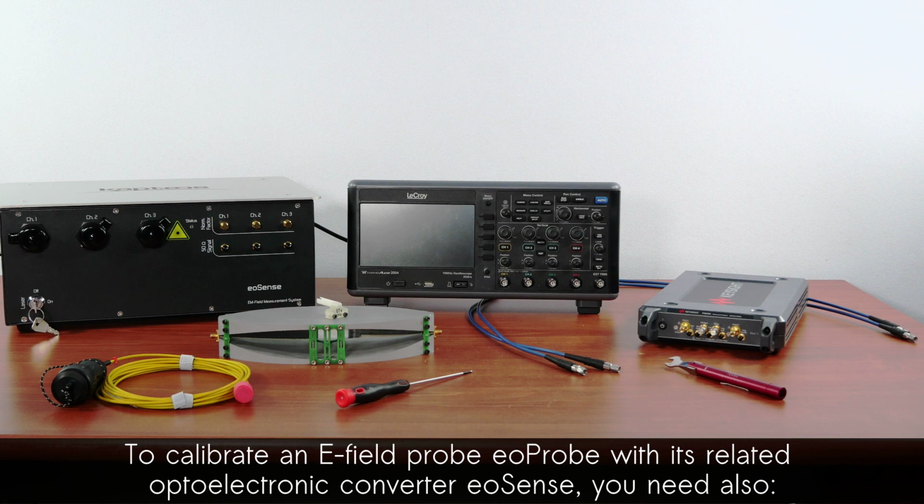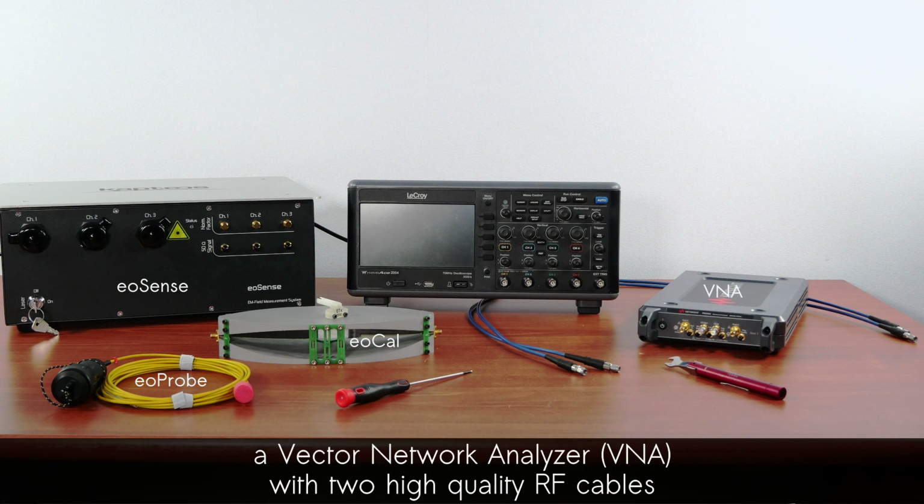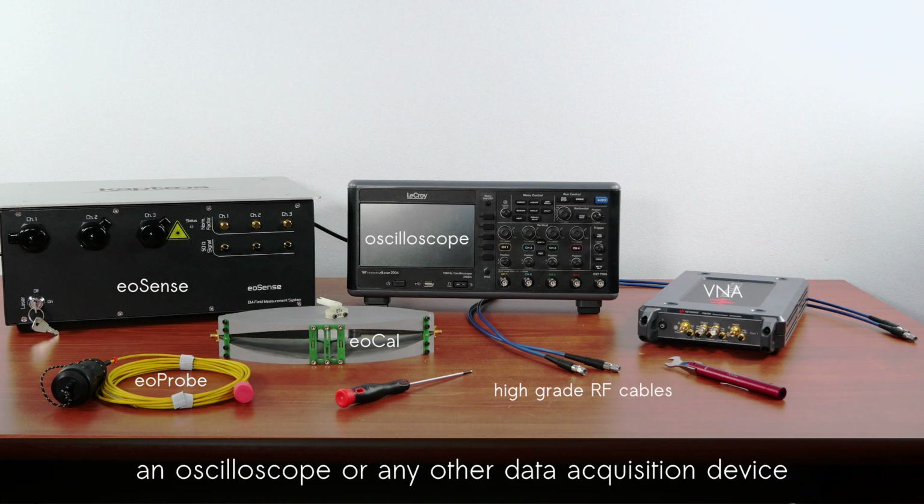To calibrate an E-field probe EO probe with its related optoelectric converter eoSense, you also need an adiabatic TEM cell eoCal, a vector network analyzer with 2 high-quality RF cables, and an oscilloscope or any other data acquisition device.